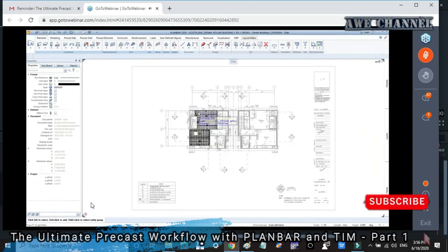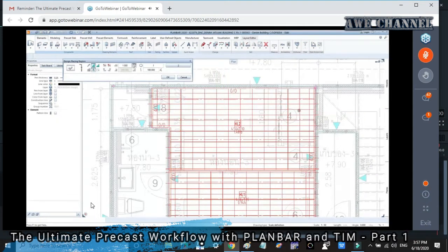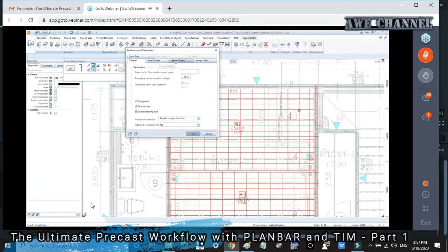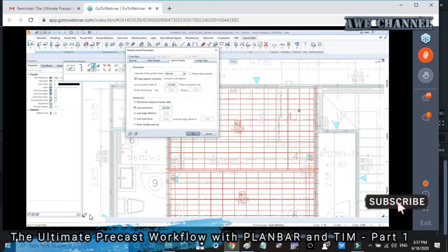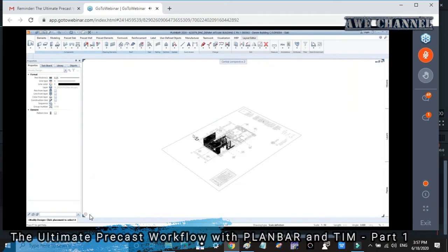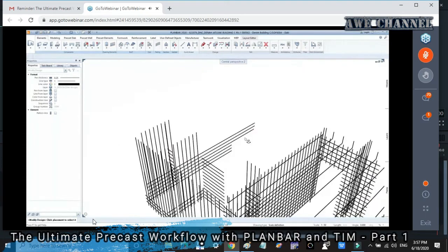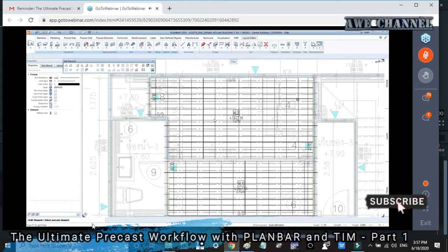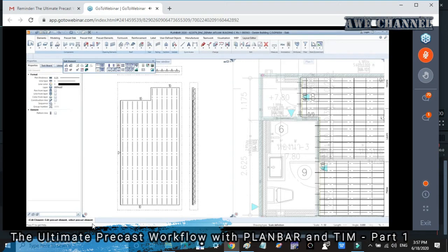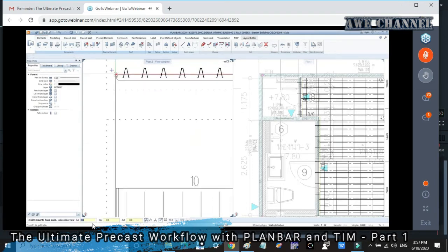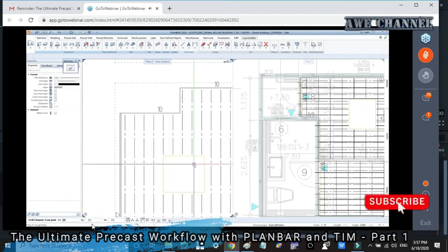Okay. Or you can go to modify design, and then from here you can go to lattice girder, and you want to lock the spacing of the girder. Let's say for example standard is 40 centimeter or maybe 60 centimeter. At the moment I need 20 or 200 actually, because I'm working in millimeters. And then I just say okay and okay. And now this is the result of the girder. It's the same actually with concrete slab as well. About opening, if I want to make an opening here, the system will automatically generate or cut out reinforcement with girder.